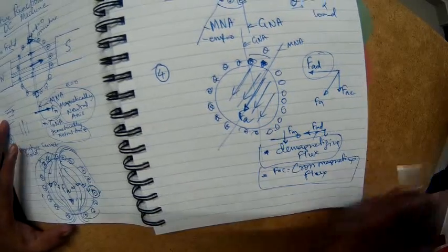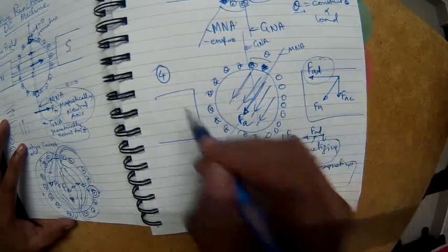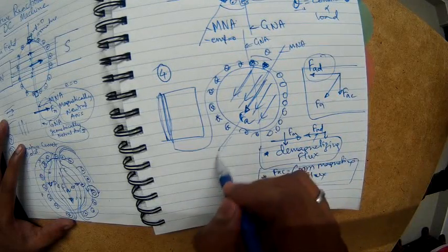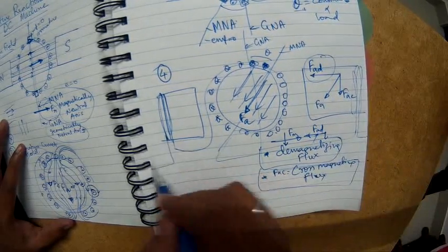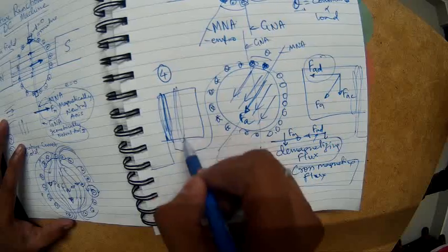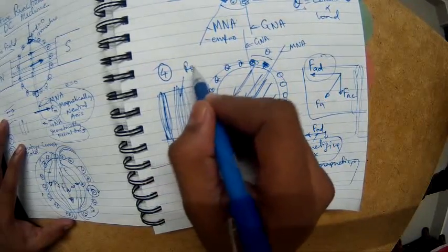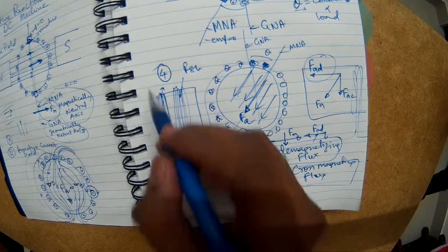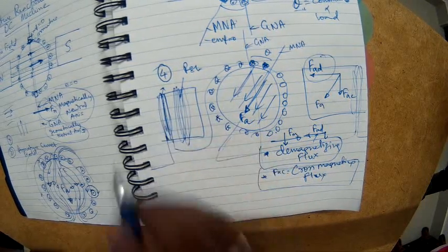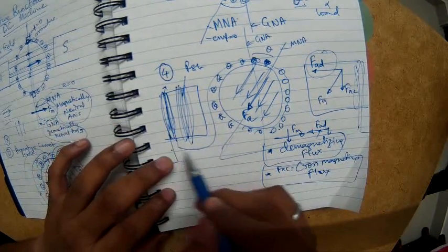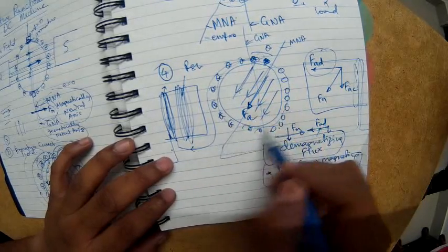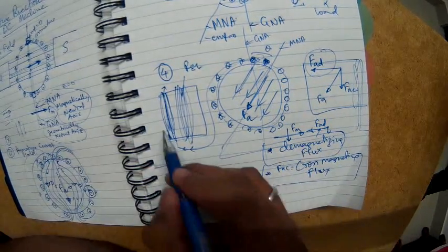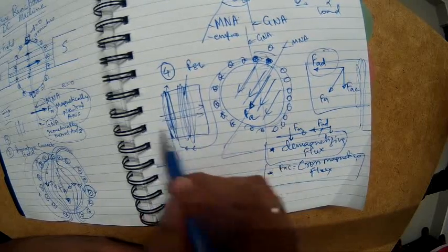The way to address this is to connect a winding in series with the armature winding. There is already a shunt field winding here, this is our RSH. This one is what is called the armature compensating winding, for compensating the armature reaction. Since this winding is in series with the armature, it carries the same current as the armature. It follows the variations and starts strengthening the field.